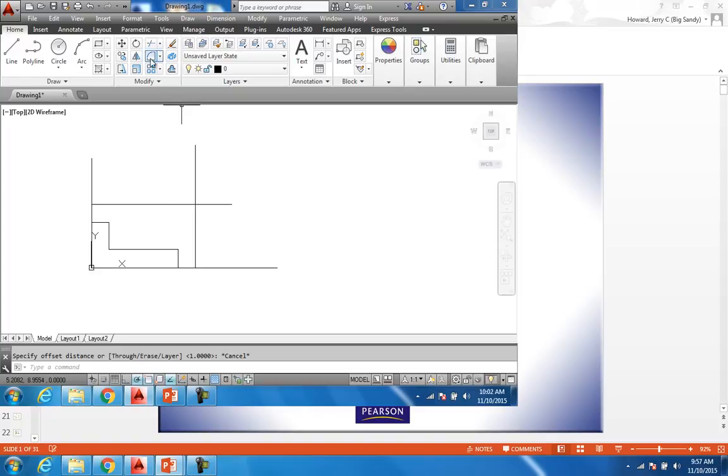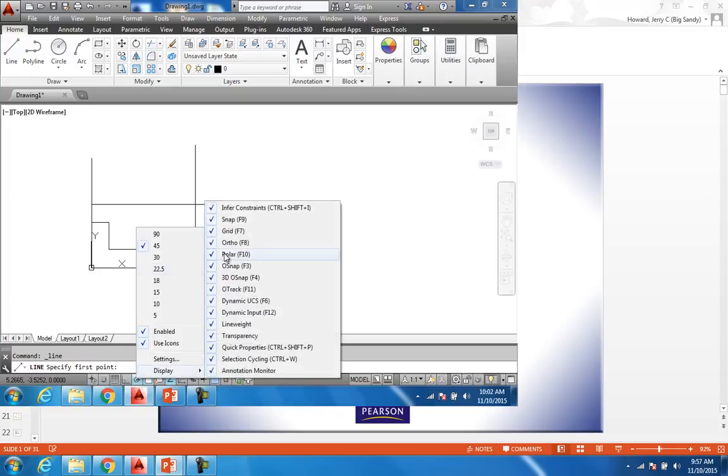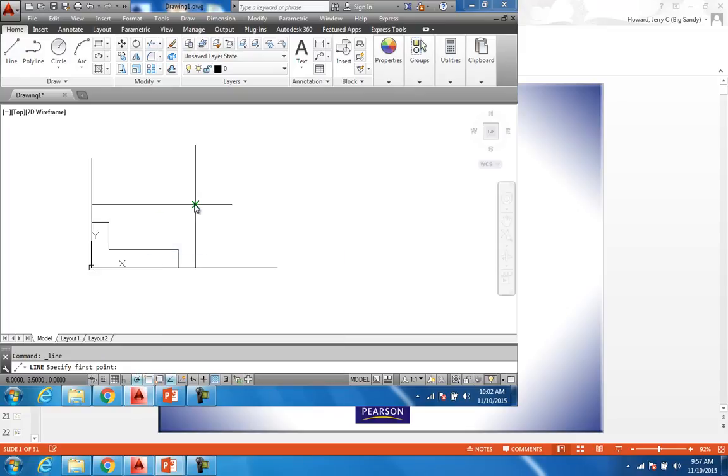So I'm going to go ahead and put my 45-degree miter line in. So hit line, come down here, and I want to go to settings. It's already set on 45. Set that in there, and I got to get a width dimension on this thing, which is 3. So I'm just going to do a quick offset of 3, and I'll put it right here. Now you see where this line right here crosses that miter line? That's where I shoot it over.